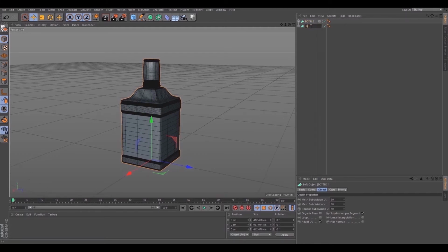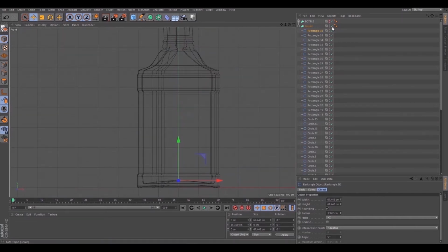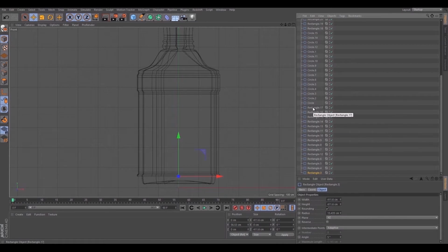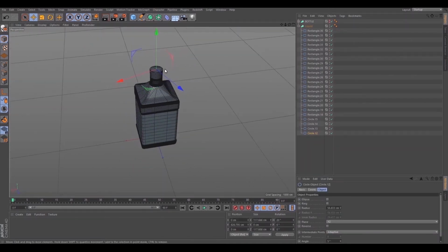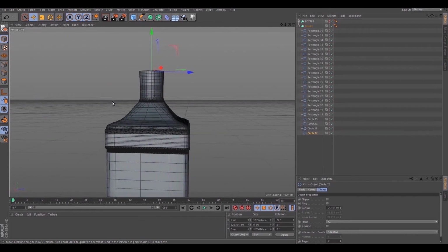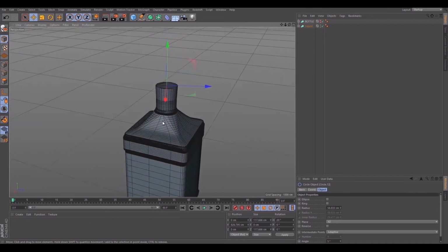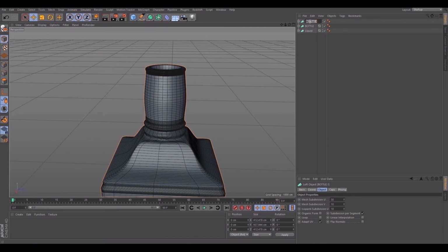Copy our bottle. We will make liquid from it by deleting outer rectangles and circles in front view. That's our liquid. Next step, create sealed cup. Copy this and delete all needless objects.